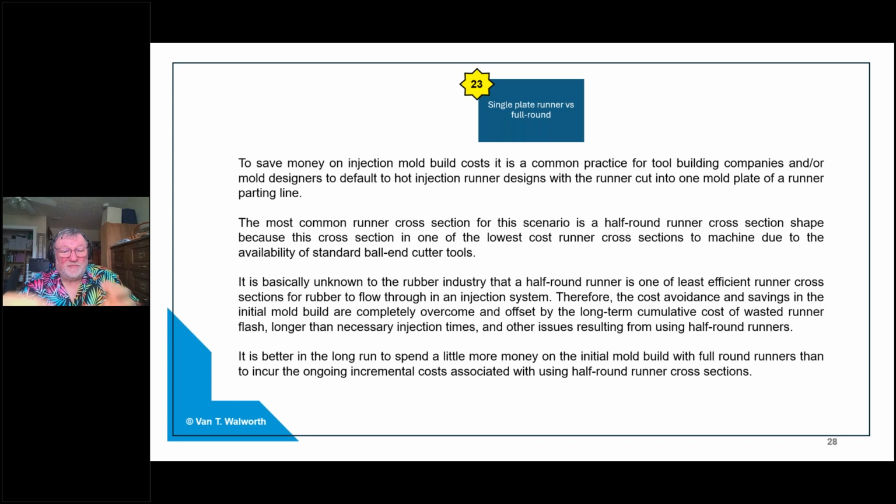And you say, well, the customer won't pay for round runners, so we can't do it. But yet you're absorbing the cost in inefficient flow, scrap that might come from that, and longer than necessary time for injection speed. You are paying for the difference in this cost, and it'll be a lot more over time than the cost of just going ahead and making it a full round to start with.